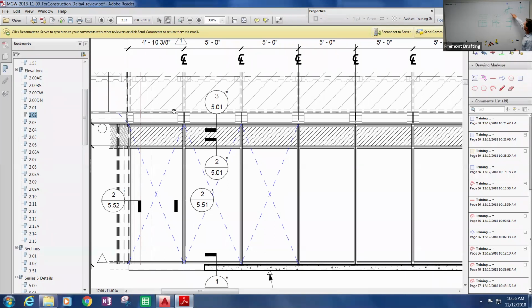This joint has to stay watertight and elastic, which is usually around 3/4 of an inch. So it's really designing for that to come over 3/4, and the seal will stretch, but it can't tear.